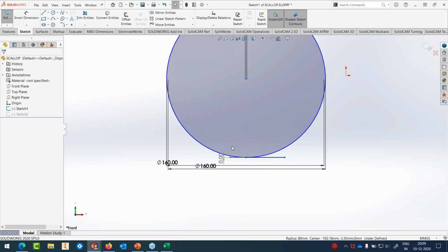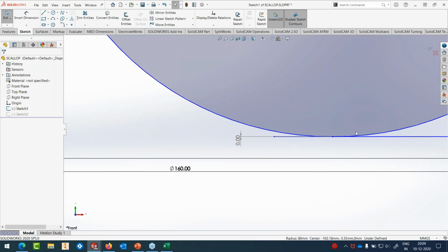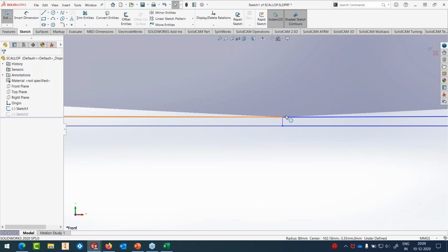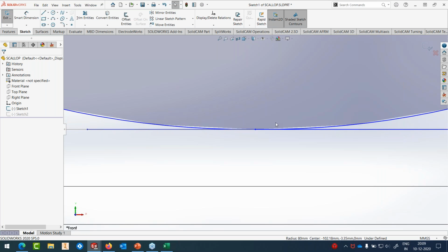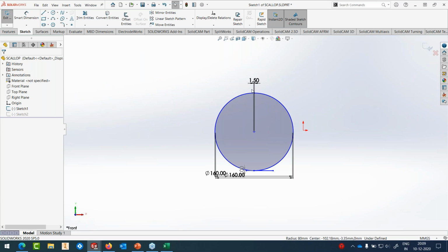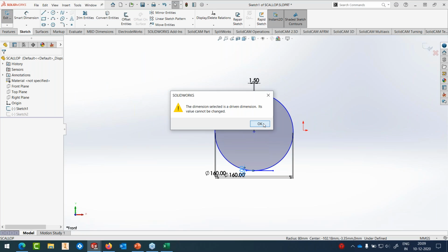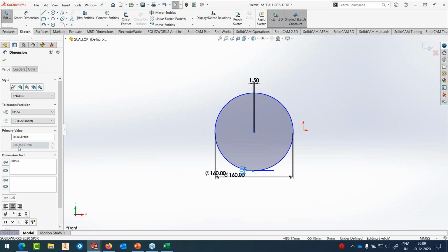Now the important thing is, if I edit the sketch, you see that I have the step down and the scallop value here. This is the scallop value, the distance of the highest crest, the mountain that forms when the tool takes a step over. At 1.5 millimeter step down, I get a scallop height of 0.003. You can see here where my mouse is, because in SolidWorks, in my sketcher, I've put a limitation of 2 decimals after the main integer. It is 0.00351. That is the scallop it generates with R80 and 1.5 millimeter step down.